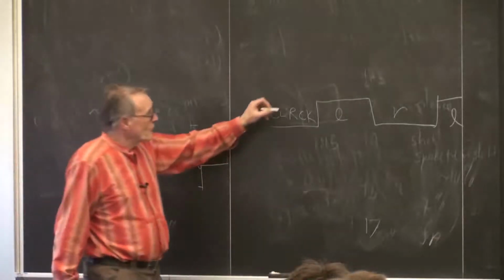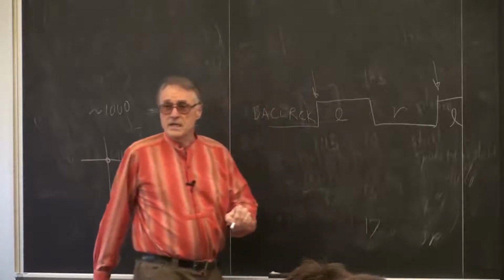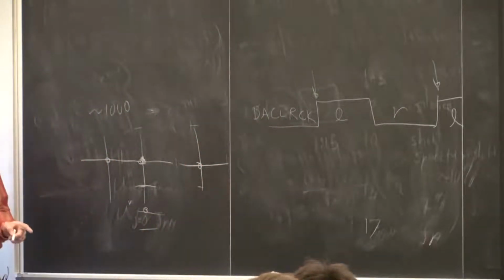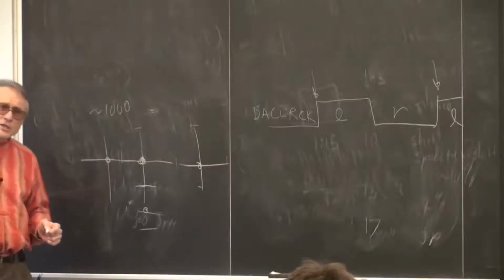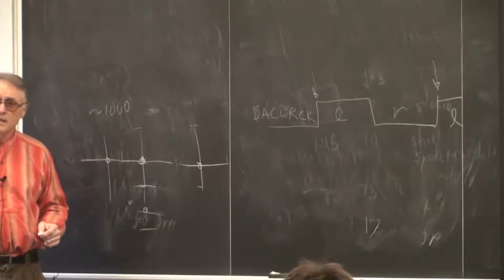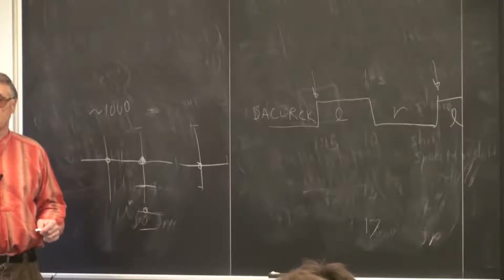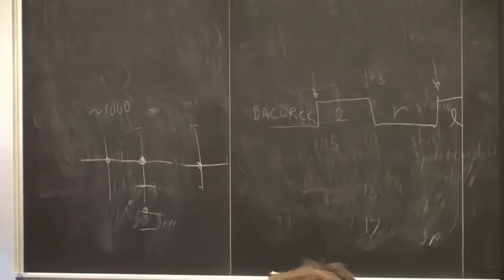But the rising edge of this clock is a synchronization point for starting the calculation of a new sample. And on average, you're going to have to calculate a sample about 50,000 times a second. If you toggle off the FIFO, you might do a burst of them and then stop. But it's a little bit of implementation dependency I don't want to talk about right now.